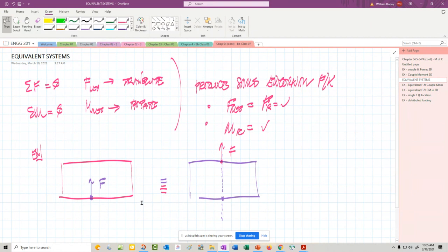Now, how can I move it up there? Well, I just can't add another force when I already have a force down here. I just can't add that second one. I need to add that force plus a counter force here of negative F. That way, this force plus that minus F give me 0, so it's as if I didn't add anything at all.